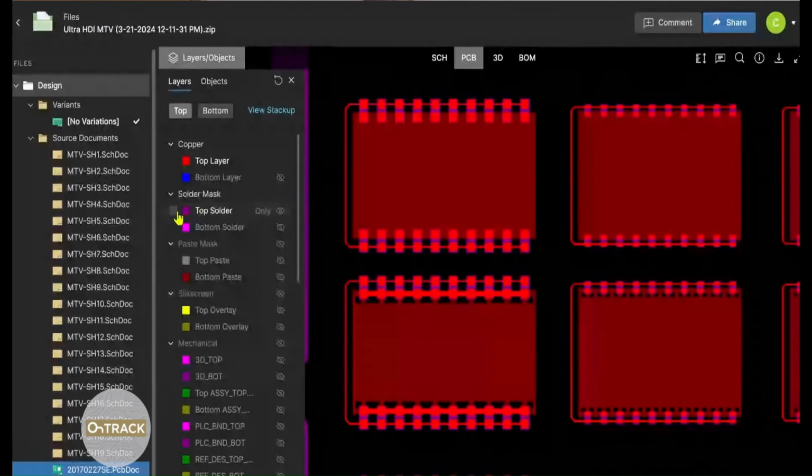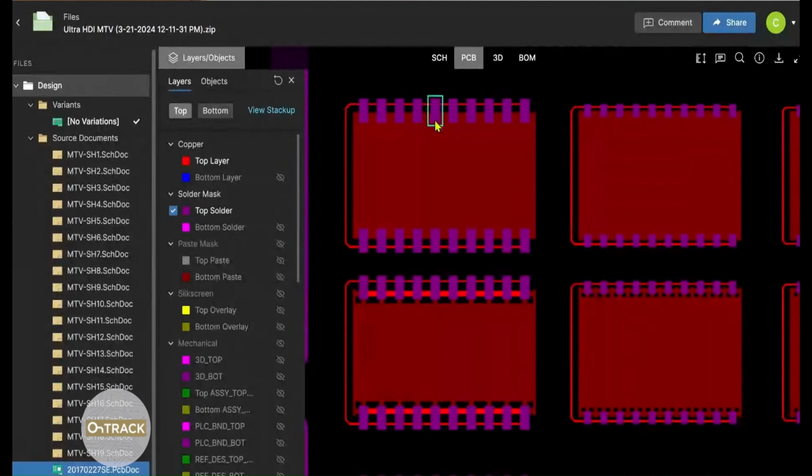So just for everyone that's listening, what we have here are some big copper pour regions, and then we have some SMD components lined up around the edge of these copper pour regions. And I see here we have some of those SMDs have a thermal attach and some of them don't. And I guess this is kind of a side-by-side comparison of the number of defects you would expect to see. Exactly. Again, that gives us the quality metrics to have the conversation with the designers and the owners of the product. Do you want to risk the defects, or can you put the thermal relief in?